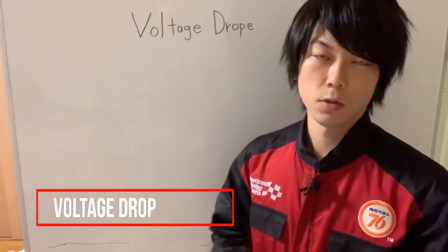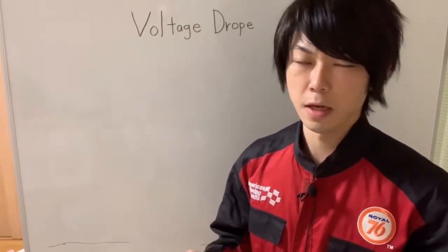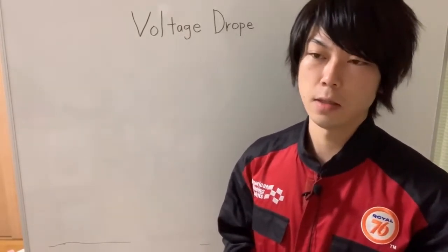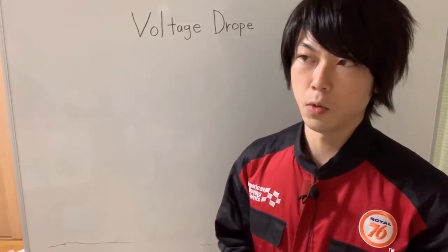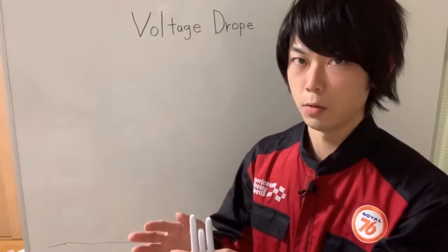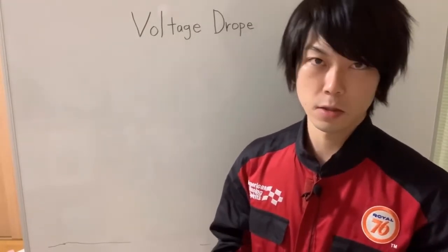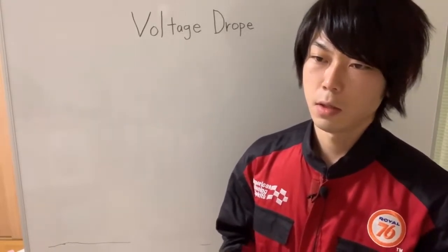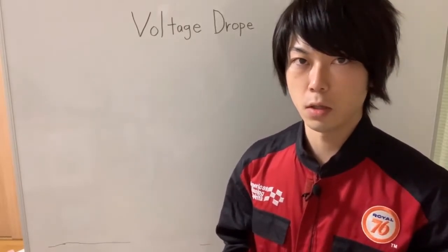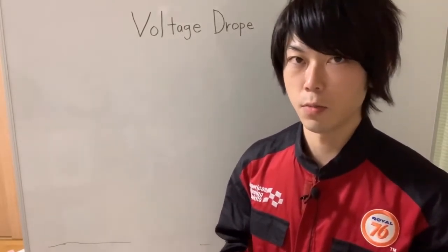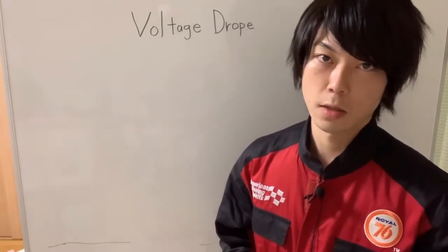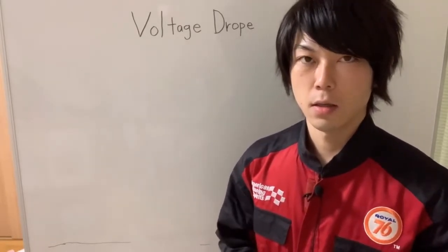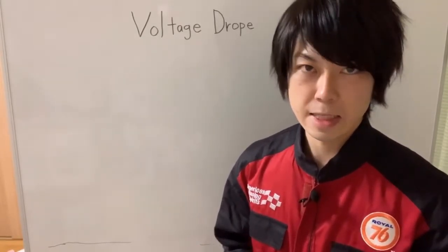So voltage drop is one of the most common failures of the electrical circuit. It can be thought of as wasted electricity. It is simply the difference between the voltage measurement at the source and the point of use. Besides the electricity you don't receive, voltage drop can cause other problems as well. If you have too much voltage drop in the circuit, it can damage the equipment you are trying to operate, like in a motor circuit, actually burn up the motor, or in the branch circuit or feeder wiring, it can cause extensive damage to the wiring.